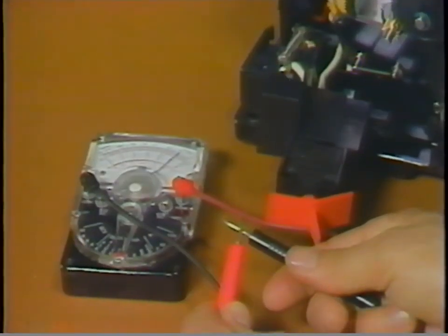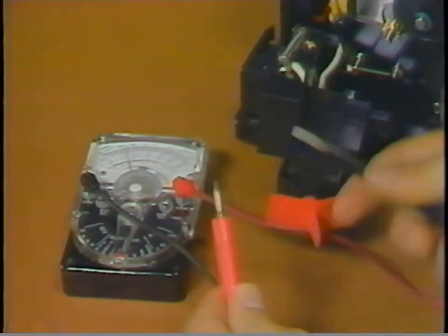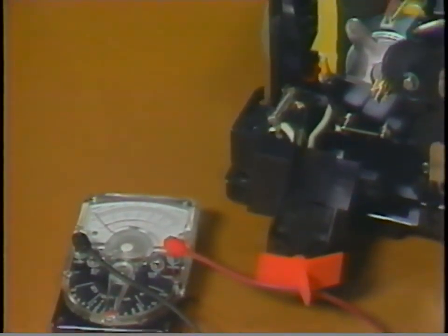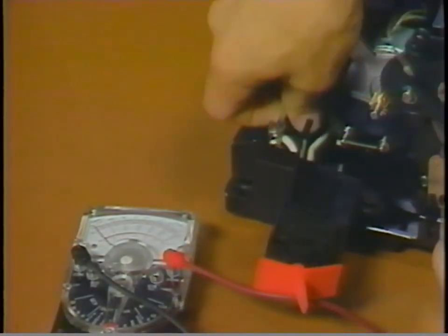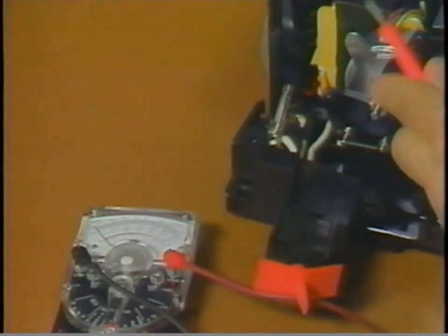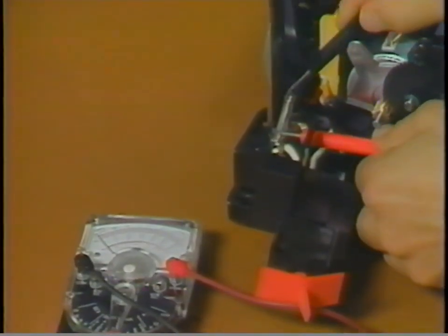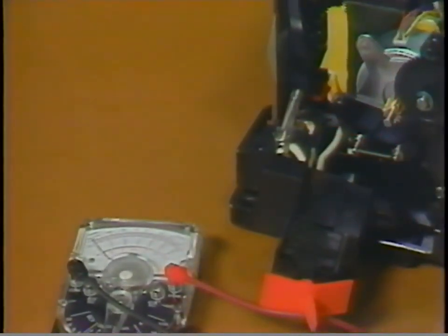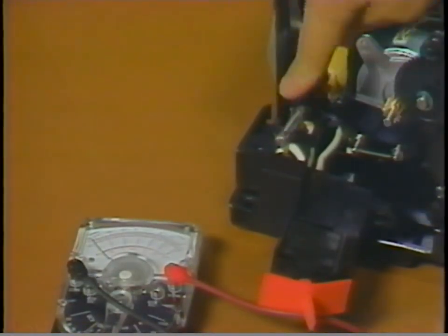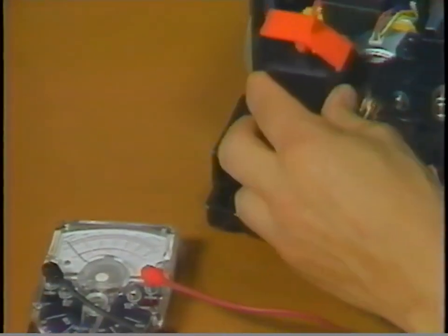Remove the fuse from the fuse block and check for continuity across the fuse. After checking the fuse and J6P, be sure all connectors are on tight and the switch tower is in place. This concludes the power supply checks.